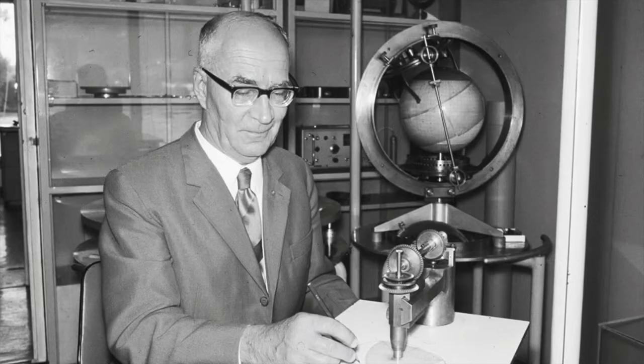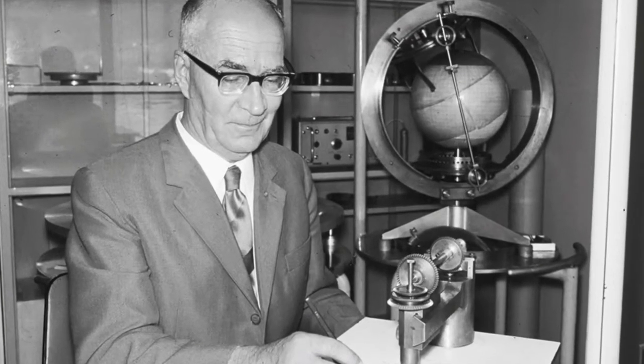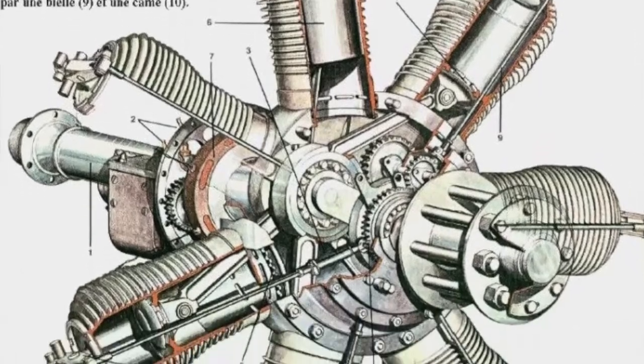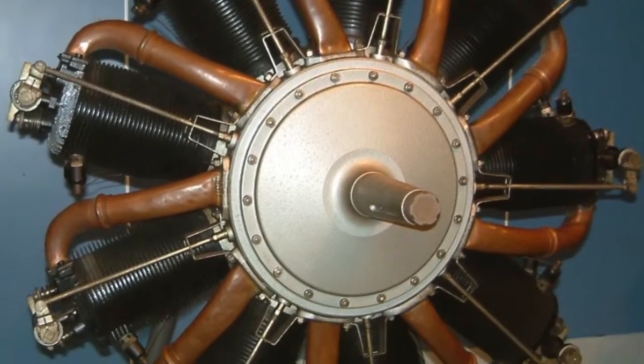The history behind it is that it was originally conceived by a man named Dr. Felix Wankel, which, as some of you might know, is referred to as the Wankel engine or the Wankel rotary engine. It was inspired by the radial engine in the 1900s during the World War I era. A lot of those planes during that time were using radial engines, but they had a problem because the engine was overheating. The way that it functions is that the engine stays still, but the crankshaft and the propeller were spinning like this, which created the overheating problem. So a way to solve it, they created the rotary engine where everything was just moving as a whole. And that solved that problem.